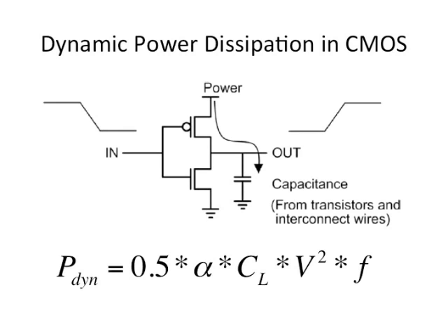Now in a synchronous design, you have a clock which captures the state of the system every cycle, because all the flops are getting triggered by the clock edge. So the inputs of the flop have to be stable for a duration of at least a setup time. If that is guaranteed, then the system will work properly.